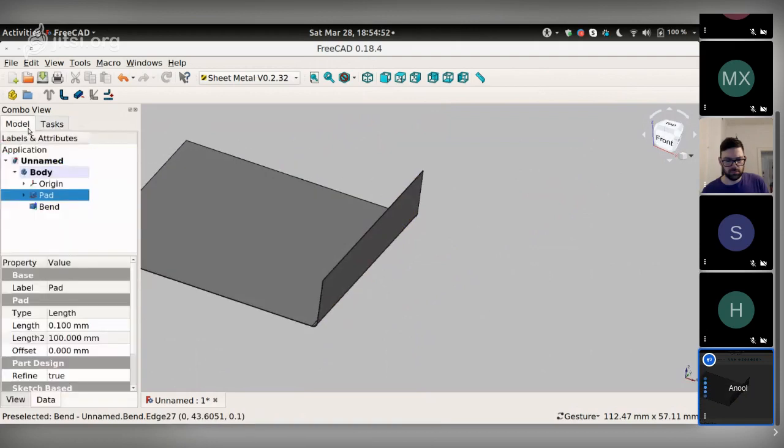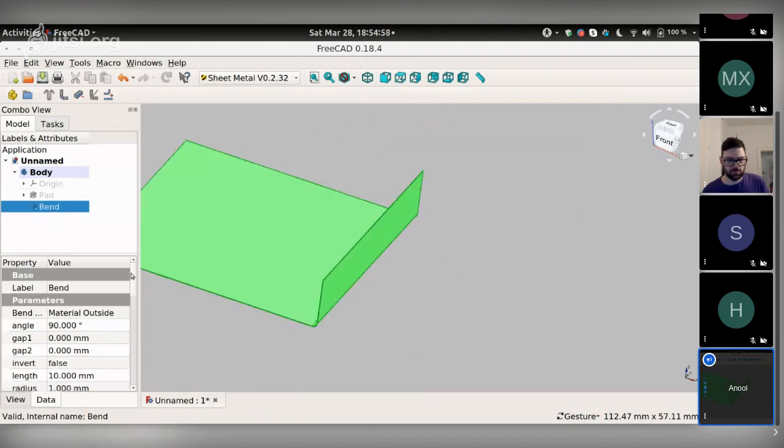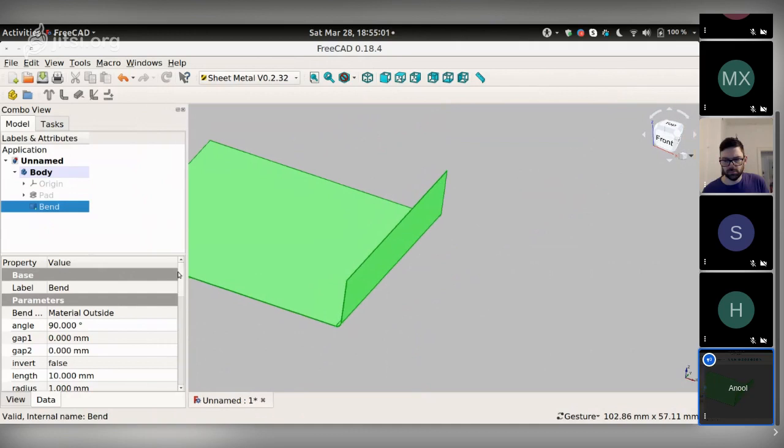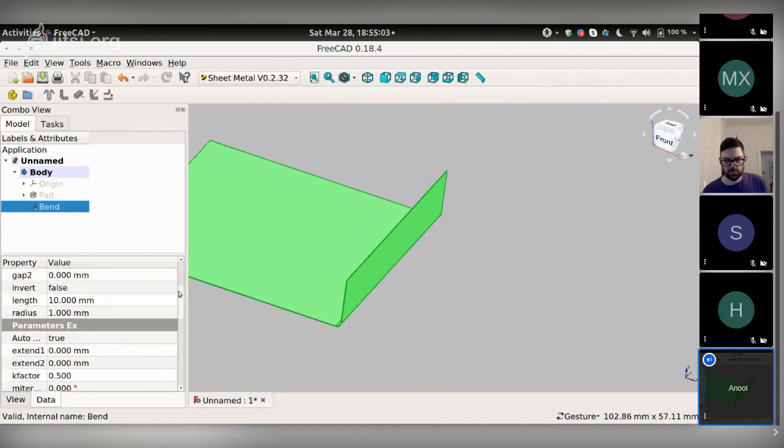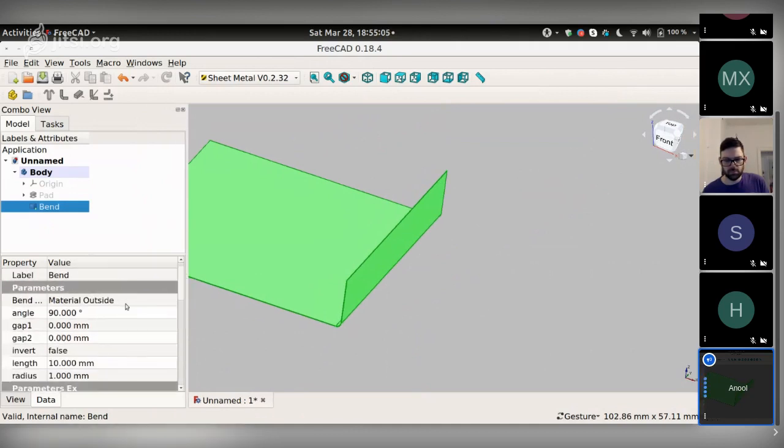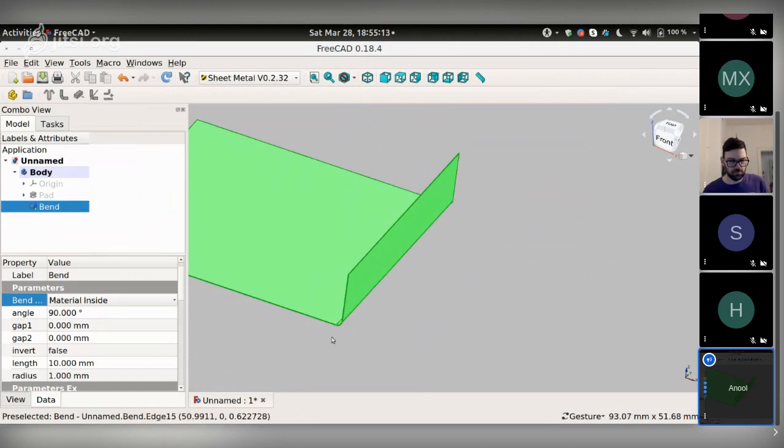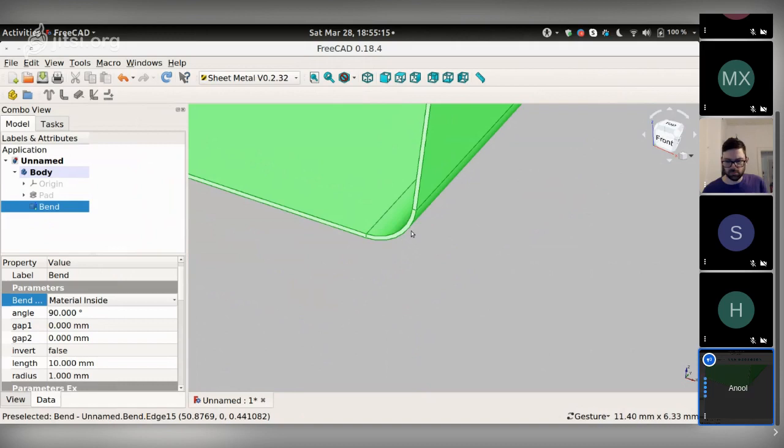And it has certain default values, which you can see here in your project, in your folder tree under bend. You'll find these options over here. So there's a material bend outside and then inside. This changes the way it uses the radius to match with the inside surface of the arc or the outside surface of the arc, for example.